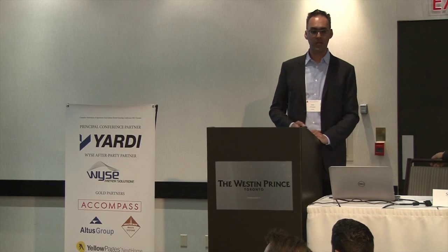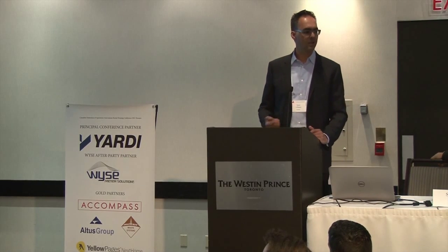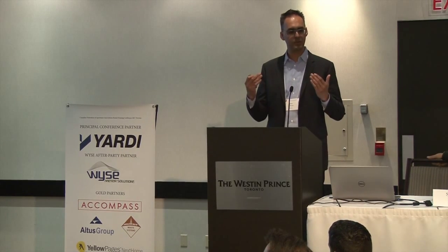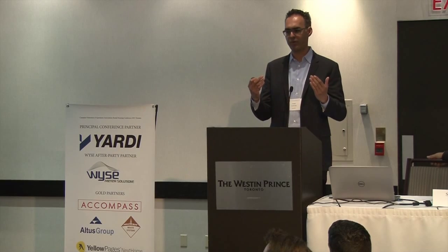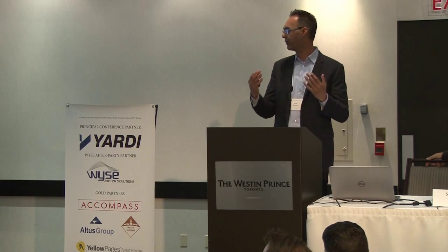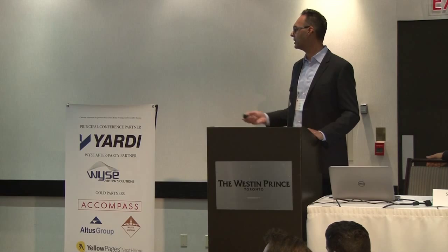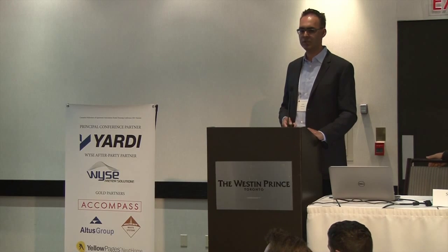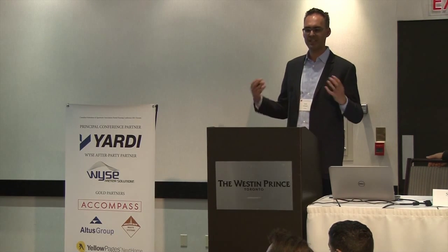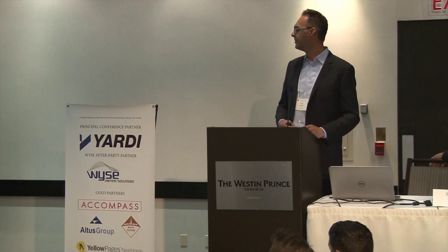They are a structural element to the wall. So as soon as they start to corrode, you lose that lateral support again. You're losing support for your bricks. You're losing that lateral support for the whole wall assembly. And so it turns into a much, much bigger issue very quickly. But this is all kind of concealed. It's tucked in the walls.